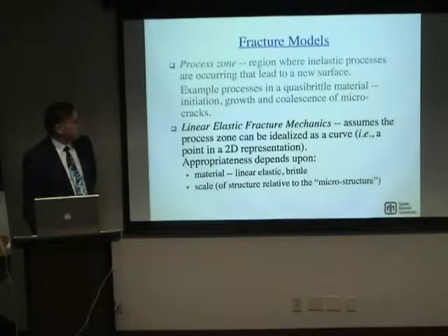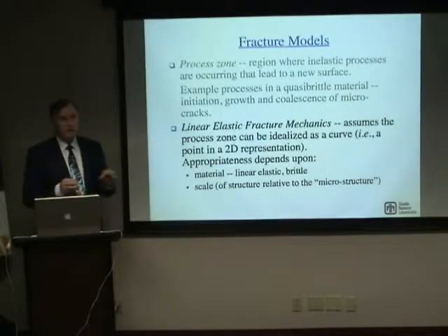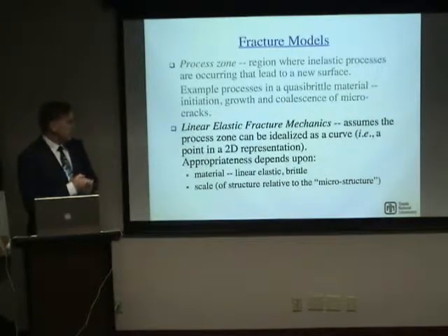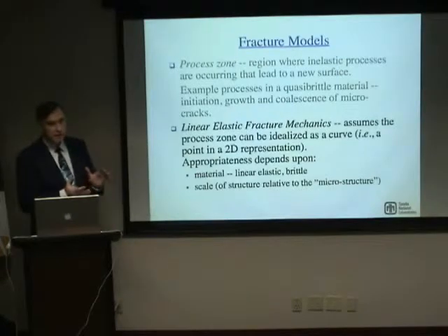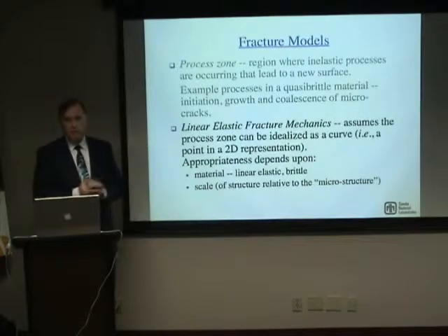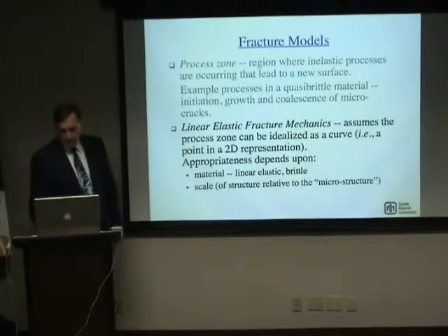So linear elastic fracture mechanics assumes that this process zone in 3D could be idealized as a curve, or in 2D, visualizing it, you would think of it as a point. So we're saying all of the inelastic processes that contribute to creating this surface can be limited to this very small region. As such, the appropriateness of this really depends not just on the material, but also the scale of the structure. So in a civil example, if you look at concrete and you're talking about beams or typical members in a building or whatever, that process zone size is significant. On the other hand, if you're talking about a concrete dam, the size of it could become relatively small compared to the size of the structure, and so you could apply linear elastic fracture mechanics.